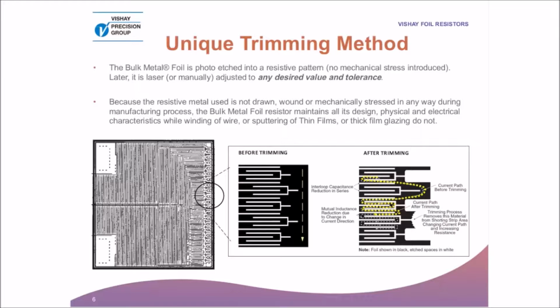Just to add to what Kevin said, the actual resolution on these foil images can come down to a few ppm of whatever normal value. All foil resistors have a self-canceling serpentine pattern that is neither inductive nor capacitive.